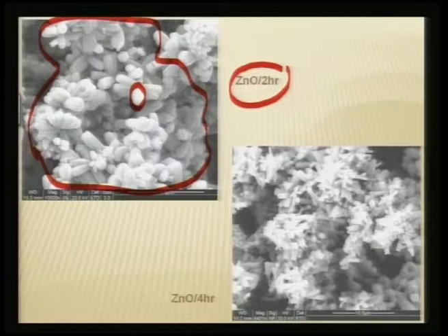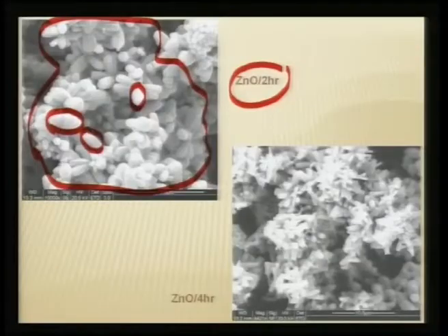Therefore, one can say that these are all tripods or tetrapods of zinc oxide, which you can see here clustering together. So, one can clearly say these are not dispersed nanorods, but they nucleate and keep growing in bunches. Nevertheless, each of the rods is nearly the same dimension as the other.